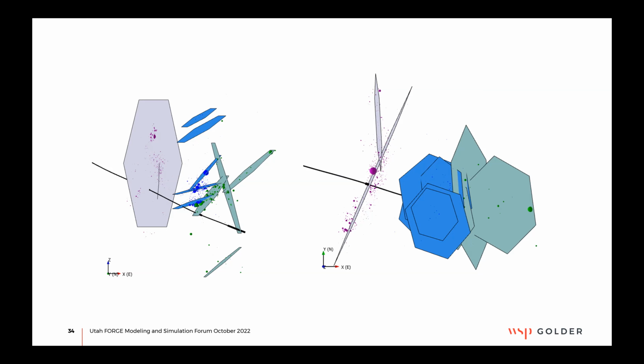Sounds great. Okay, Colin says here: I have a comment on the previous question, and then I have a question to the speaker. The comment to the previous questioner was, I think it may be misleading to try and seek an analogy between shales and granite. Shales are extremely anisotropic, and if we're to believe the DFN that was shown right at the beginning of this talk, this granite is much more fractured than a normal unconventional shale. So I'd issue a note of caution to assume the granite behaves like an unconventional shale.